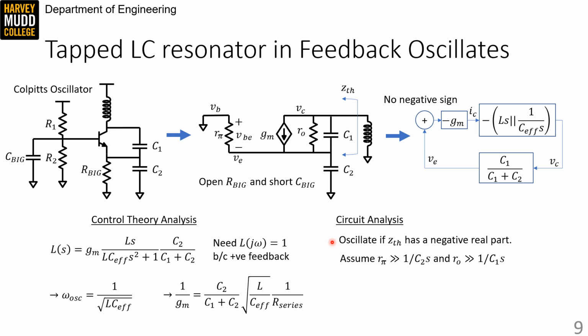And so the general idea there is just that if an inductor and a capacitor that are hooked together with 0 resistance will oscillate forever. And so this GM generator is canceling out the effect of any real resistance that's in the inductor or your capacitor network.